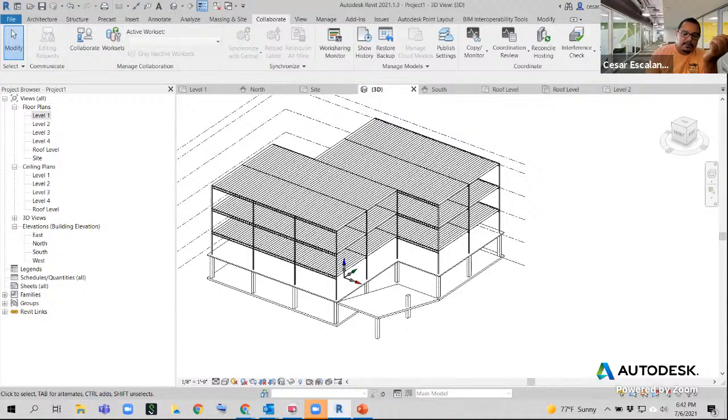There's an agreement where the architect tenders the ownership of the edge of slab up to the end of schematic design. And then during DD, structural is the owner, and then the ownership switches. And then we use visibility graphics to display or not display the redundant objects.